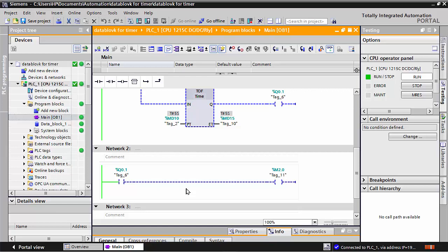It depends on your machine logic, what type of machine. Somewhere it has a counting purpose, and some machines are used for filling purposes. If you are filling bottles, for example water or juice, you will fix the timers, 2 seconds after input close, 3 seconds after input close, 5 seconds after input close.